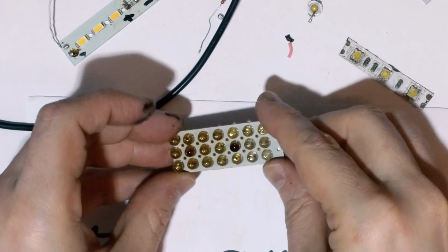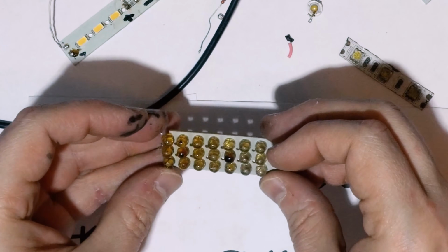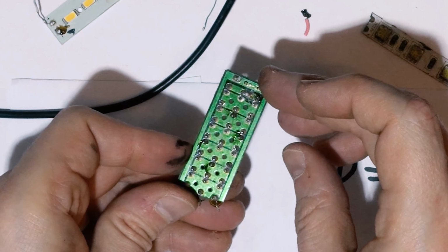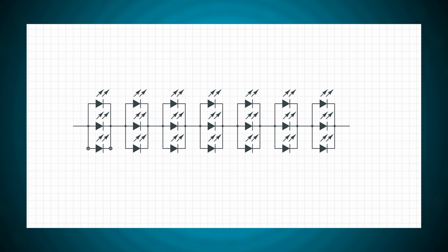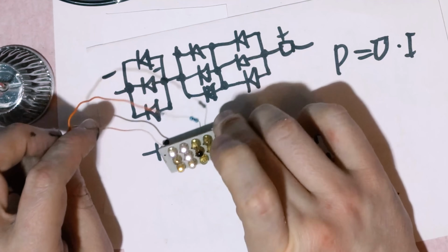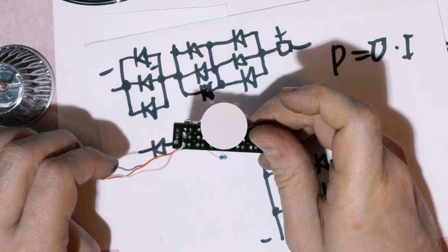Okay, we also got these LEDs left. This used to be a 220 volts AC lamp. Here we got LEDs grouped by 3 and then connected in series. Here's the schematic. 7 LEDs in series, that means again, we cannot power this circuit from 12 volts. But we can power them if they are grouped by 3. Like this. This is gonna be 3 by 3. Power on. Working. Only some of LEDs are dead, shorted, but that's obvious.